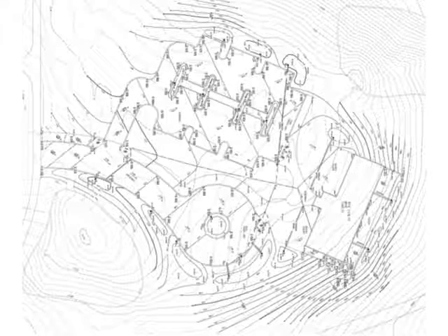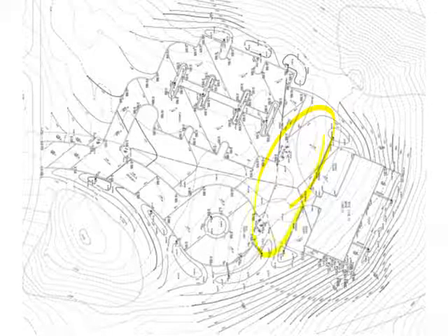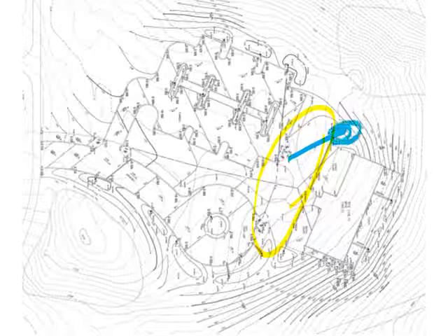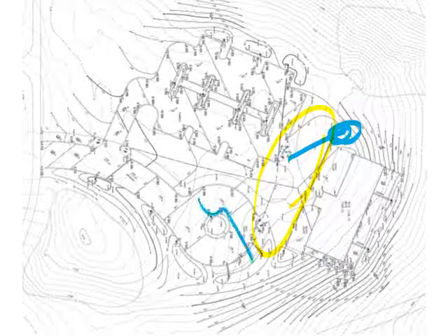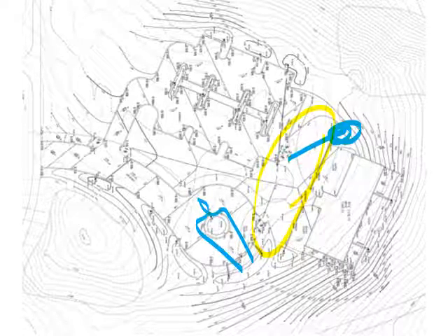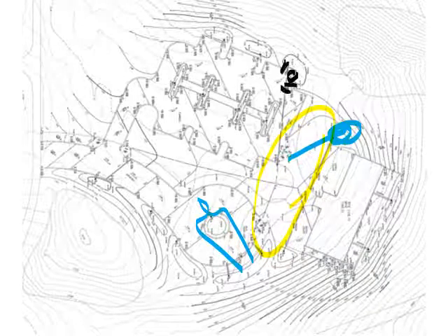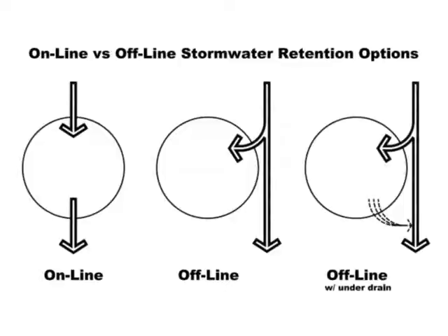And of course, we provided you with a few other plans you can take a look at. And you might discover that under different circumstances, you might want to take this plaza area, break it up. Maybe you're going to have a trench drain that runs water over to one side. We've already talked about how you might have an overflow system around the drop-offs, and how you might have a drop inlet at the corner with two curb cuts on each side that allows water to flow into your retention area. So these are the basic methods for making offline systems.